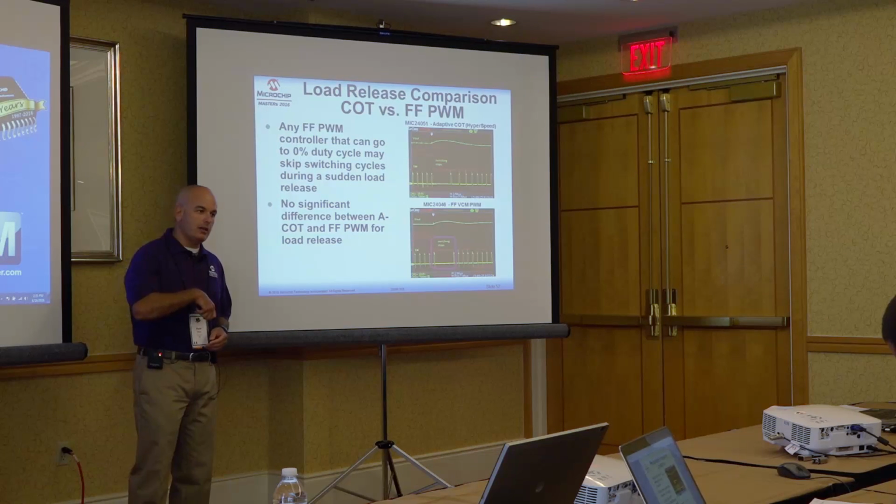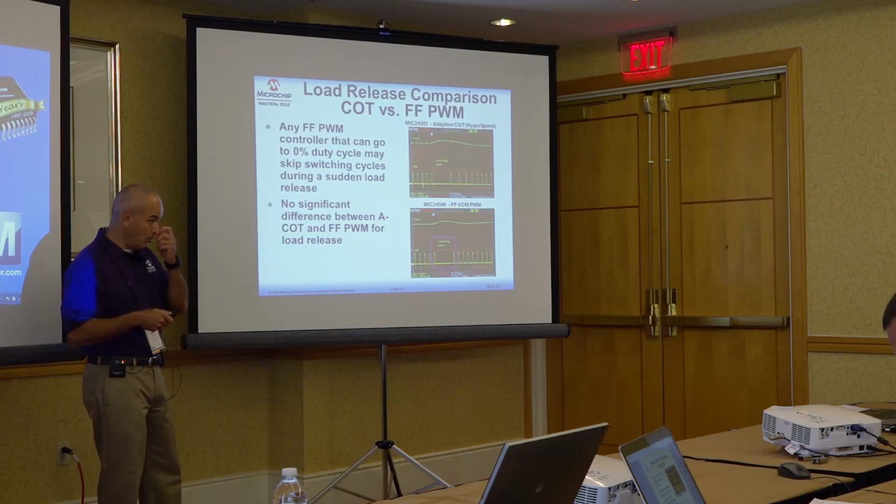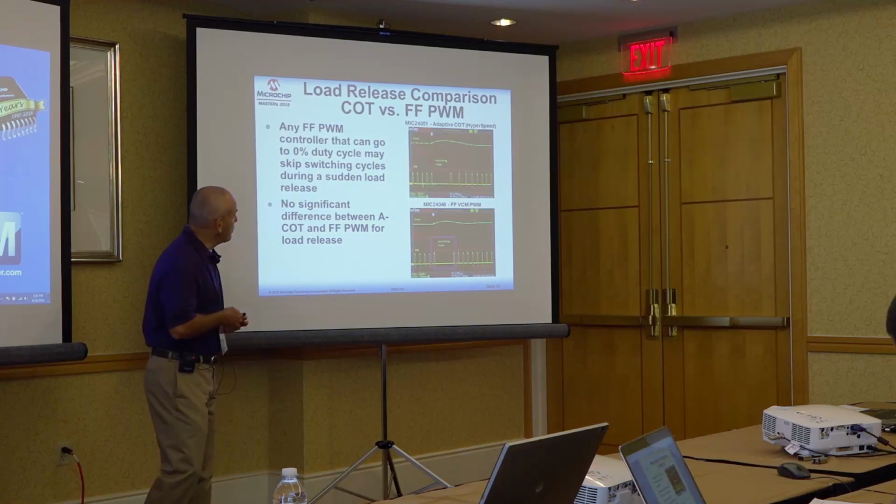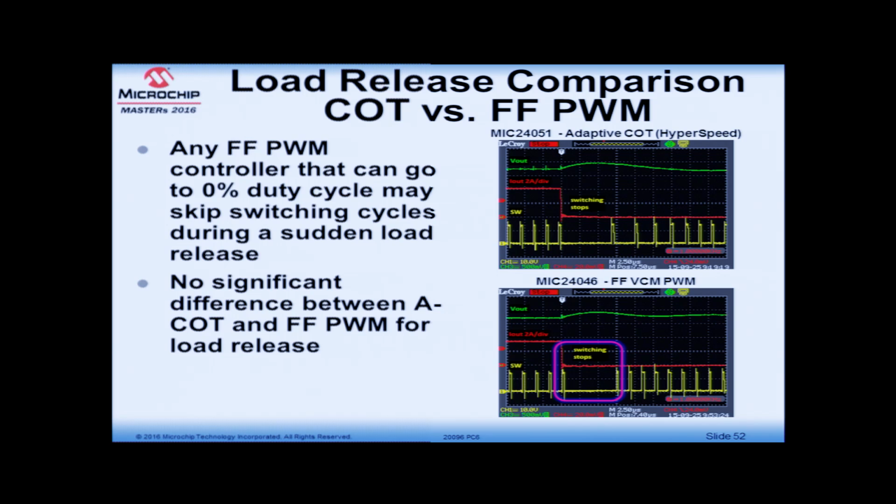We look at the other side of the load transient, so the load release. For load release, what a constant on-time part does: the output voltage, so the feedback, goes above the regulation threshold, so it has to wait for the output voltage to recover to hit the regulation threshold again.